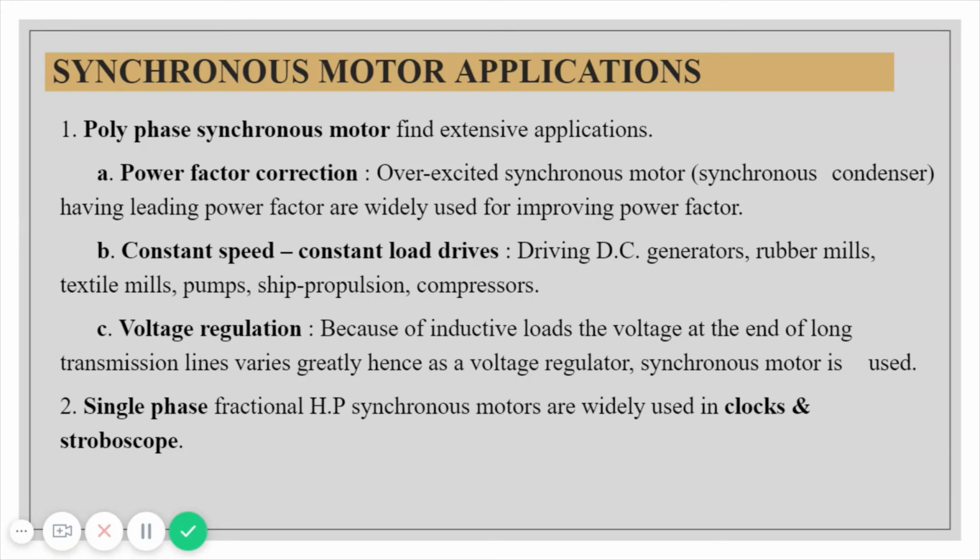Because of inductive loads, the voltage at the end of long transmission lines varies greatly. Hence, a synchronous motor is used as a voltage regulator. And single phase fractional HP synchronous motors are widely used in clocks and stroboscopes.